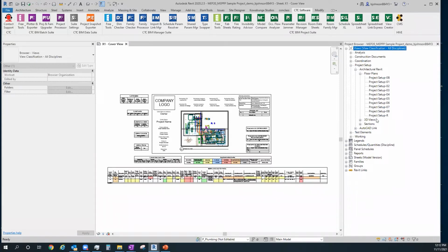It wipes out those levels. It wipes out the existing views of all those extra levels. So if I only had a 4-level building, I'd want to get rid of 5 through 8. I would do that with the Dynamo script and have it purge those plus all of the other view types that are in there based on those levels. It'll also grab all the sheets that are not applied to those views as well. So I just did that in a training class a few weeks ago and it worked out rather well. Previous Dynamo scripts, not so much, but this one actually is pretty refined and seems to do what it's supposed to do. We do have sections in our model.